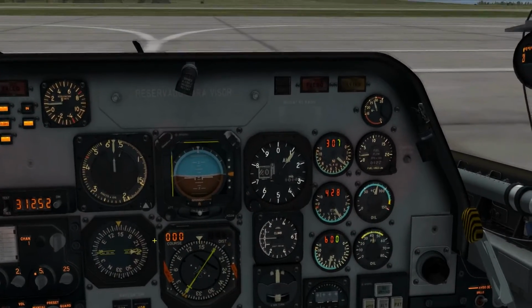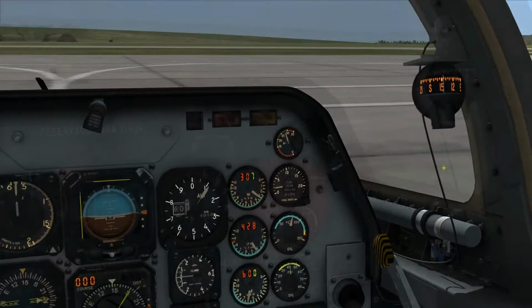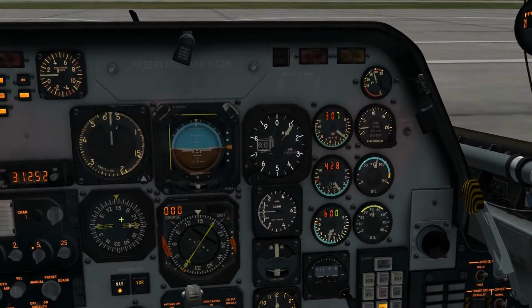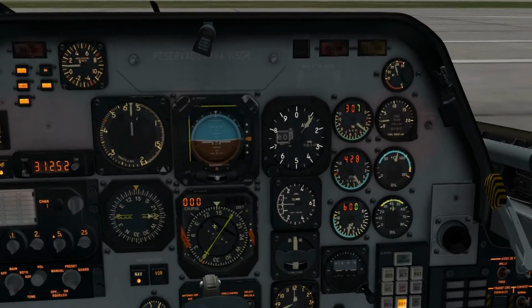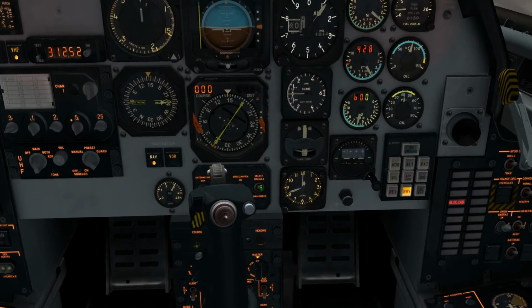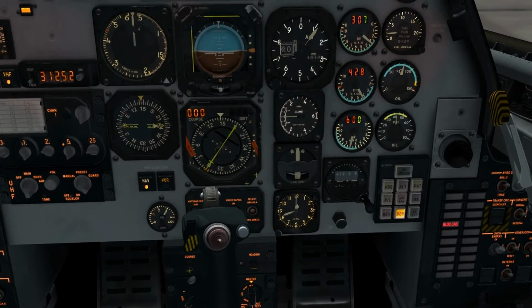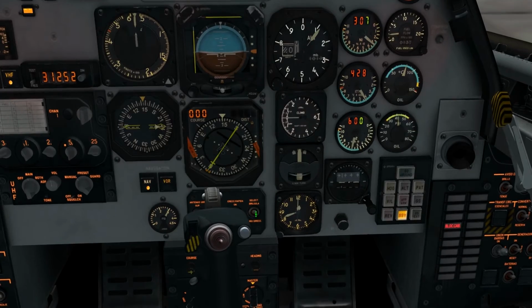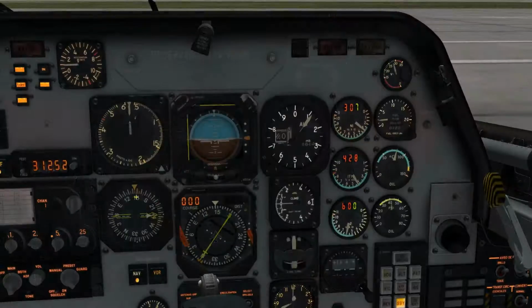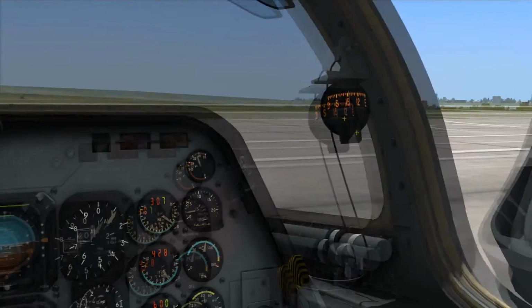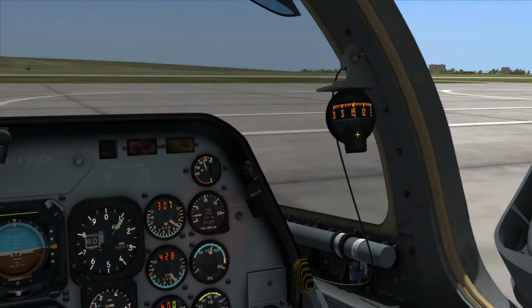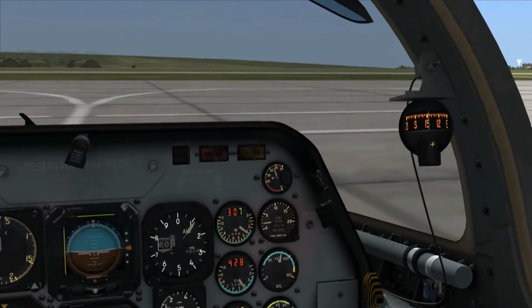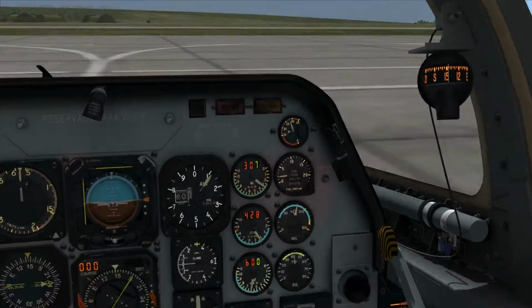The gyroscopes have been set between them. This is the directional gyro, and this is the horizontal indicator. You can select with this button which instrument to slave it to. Now it's currently slaved to the compass, marking the same, and the compass, the only instrument of the plane that does not need any energy to work, marking the same.